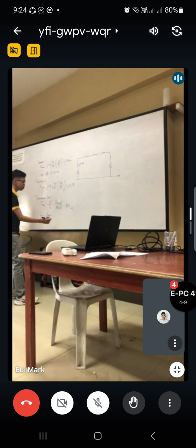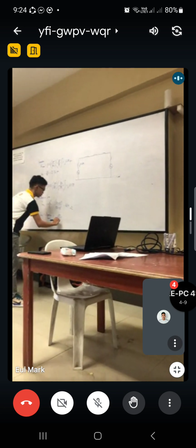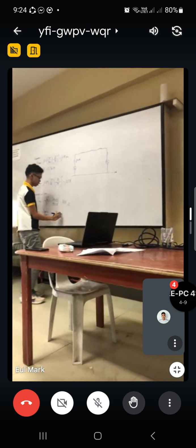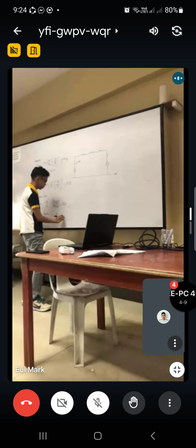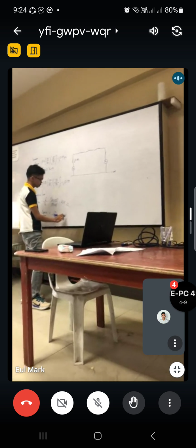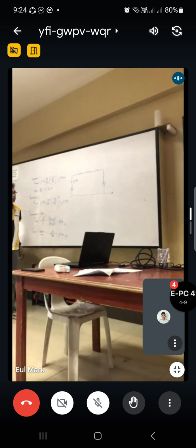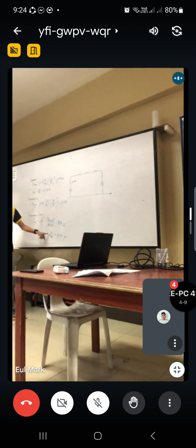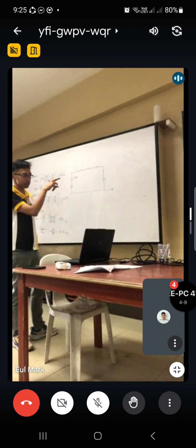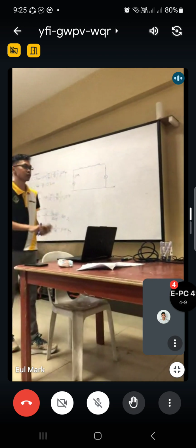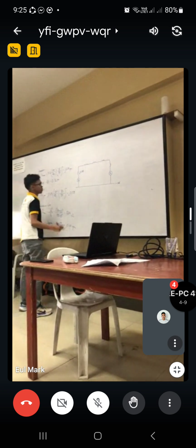This is equal to j50 over 484, which is j0.103 per unit. Of course, the ohm cancels. j50 ohms is no longer per unit; if it's j50 per unit, it wouldn't be in ohms. It's usually j50 ohms.